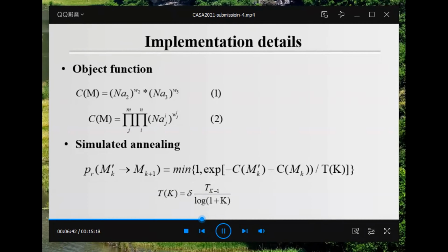To quickly obtain a suitable solution, we explain the classical heuristic search algorithm, simulated annealing, which is commonly used in furniture arrangement and building layout planning. We first define the objective function in the heuristic process using the evaluation indicators, and then construct the simulated annealing model.